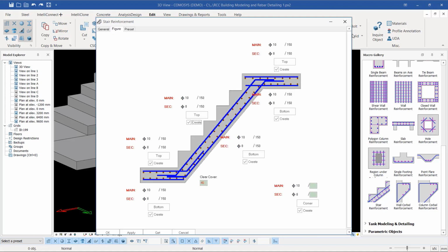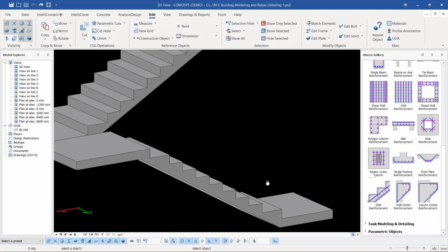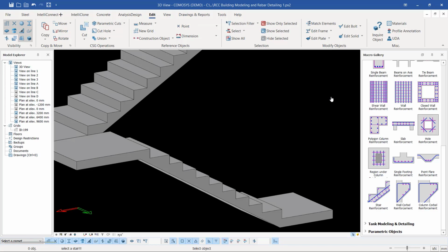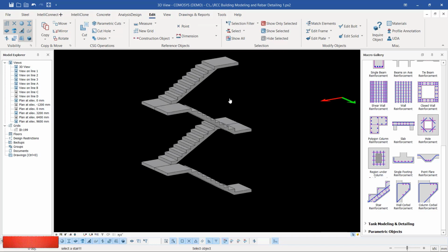Now, once you've done so, I'll just go ahead and click on that tool once again. Once you've created your settings and decided that the particular settings you've made work best for you, and you've saved them, you just select the setting you've saved and click load. Let me show you that. The moment you select the settings you need, you click load to load all the settings, then come here and click apply and OK, and you'll be able to make the settings active and apply them on this particular staircase.